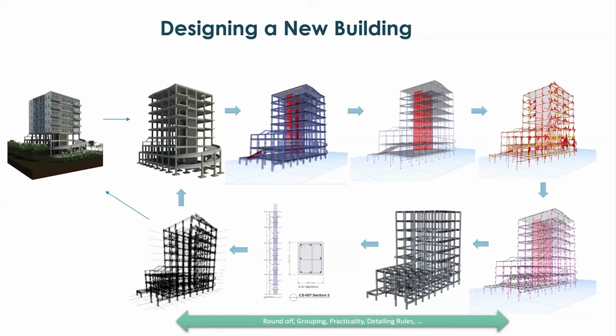But after the analysis, from design to detailing, the results kind of break out or get mixed together, and the final output will not be the same as the analysis would indicate. The analysis would indicate each column at every floor to be different, but detailing will say no, 10 floors are the same, next 10 floors are the same. That produces a structure which is different from what we designed, and now the rest of the structure will not be what we started with.